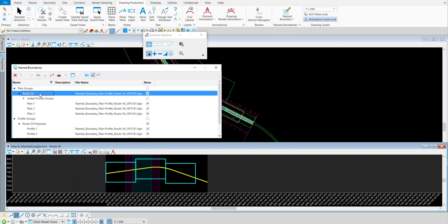If you select the plan, it's going to tell us we can get a plan drawing or a plan profile drawing. We want to do the plan profile drawing. It's very important that you check this show the create drawing dialog box on before you do anything. This little pencil squiggly mark. And then we'll come back here and we'll create that plan profile drawing.